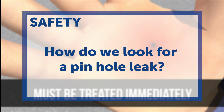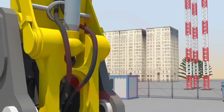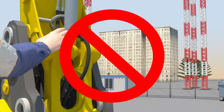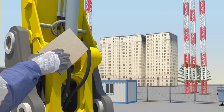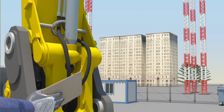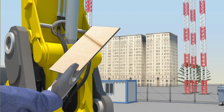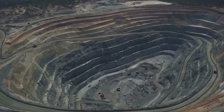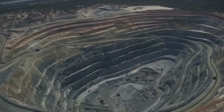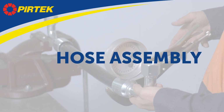How do we look for a pinhole hose leak? Never run your hands along the hose, even if you are wearing gloves. Your gloves will not protect you. To locate the leak, pass a piece of cardboard over the area or use a mirror where you suspect the leak may be. Always use extreme caution. The Mines Hose Management Plan should aim for the in-service inspection and assessment to discard the hose prior to a catastrophic in-service failure occurring.